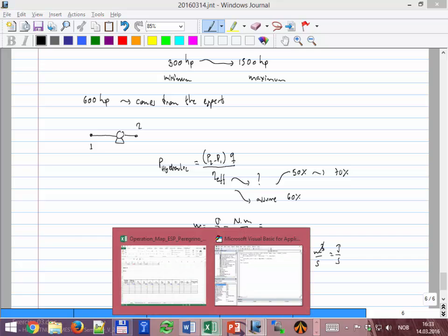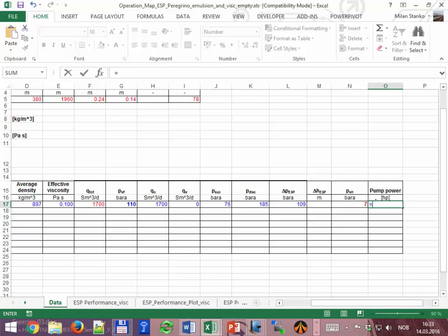You see, these things, you use them in your normal life. Okay, so let's see, P discharge minus P suction, that's in bar, so to take it to pascals I have to multiply by 1e5, and then times the rate, and the total rate is here. The rate is per day, so I have to convert to seconds and divide by that. Is it correct? Like that?